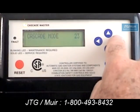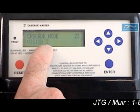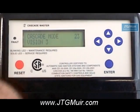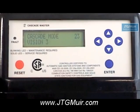The other option is Vision 3. Vision 3 is an external panel that allows you to lead, lag, and stage up to 8 boilers. In that case, we would go back to function number 15 and we'd program each boiler with an address. One boiler would be 1, 2, 3, and 4 accordingly.